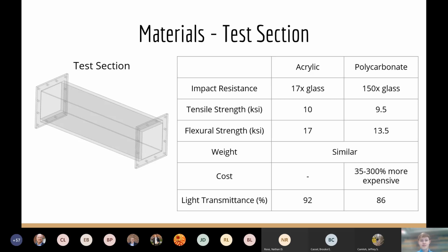The rest of the flume, however, does not have to be clear. Fiberglass was considered, but making large fiberglass parts is too time-consuming and too expensive to outsource. PVC is the perfect balance between strength and cost in this case. Also, newly rinsed PVC and acrylic should not release microplastics within operating temperature, meaning that these materials are safe for the fish. The PVC sheets for the top were chosen because the flume requires complex geometry, but for the rest of the flume, PVC pipe was used.